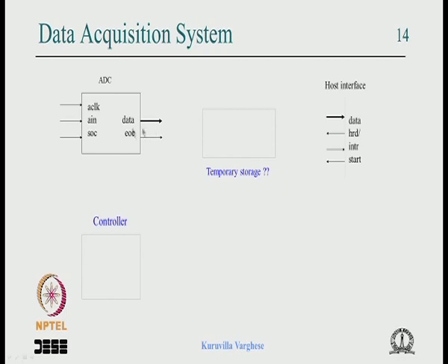We are getting the analog samples and putting them in a sequence: the first sample comes here, the second sample here, the third sample here and so on, and the host needs to read in the same sequence. There is no point in reading the 5th sample, 7th sample, 2nd sample and so on. There is no random access, it is a one way flow. So DPRAM is a costly solution, and most of its features are not required.